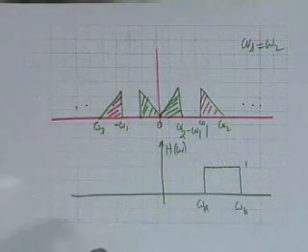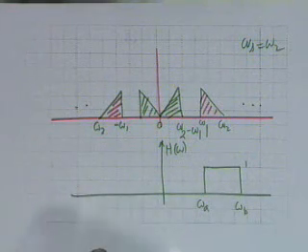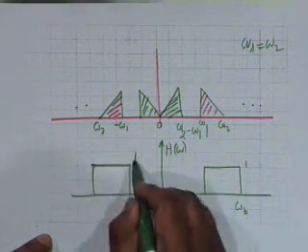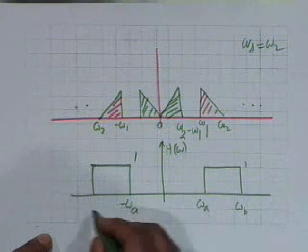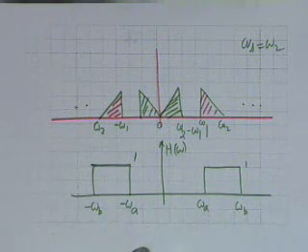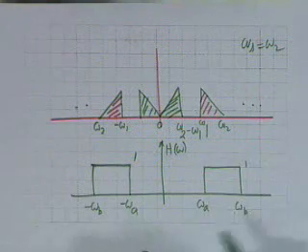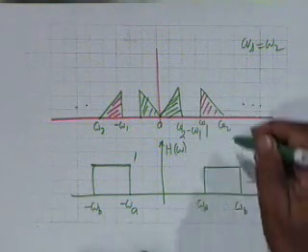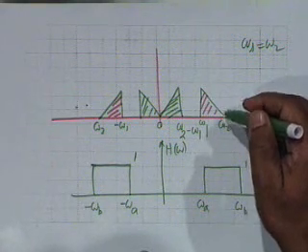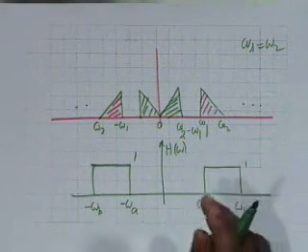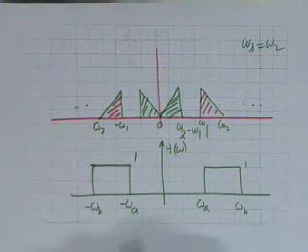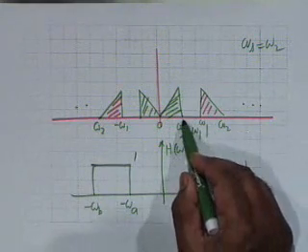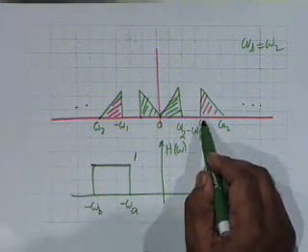Instead of a low pass filter now, we want a band pass filter, and therefore what we need is this, 1, minus omega A, minus omega B. And obviously the band pass filter will do if omega A is equal to omega 1 and omega B is equal to omega 2, right? Now you can have a little guard band on this. Actually omega A does not have to be equal to omega 1. Omega A can lie between omega 2 minus omega 1 and omega 1.